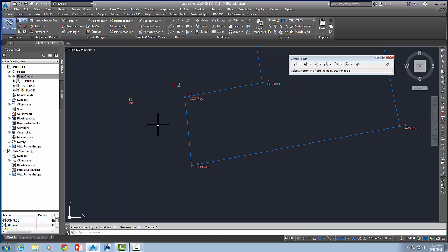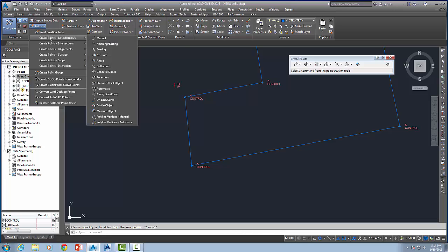So we'll do one more from 5. Another setup with a different type of angle type. This one is a new one. It's called a deflection angle. Deflection angle is defined as the prolongation of the backsight. So what it's going to do is actually backsight 4. However, it's going to really look at it from a 180 direction.